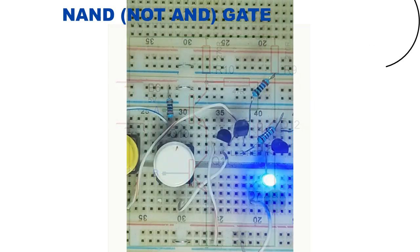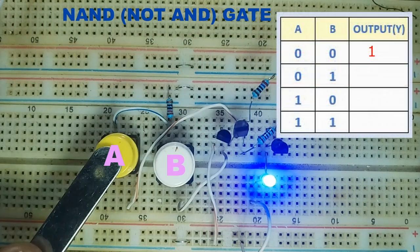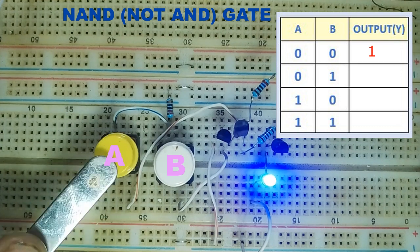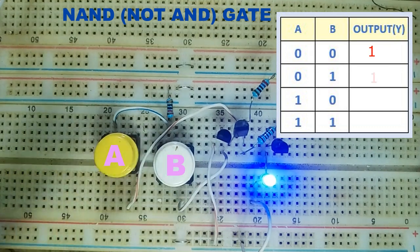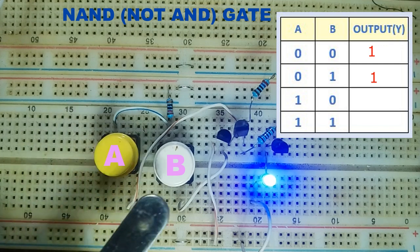The circuit on the breadboard is also implemented using 3 transistors. The first 2 form the AND gate and the third one is for inverting the output. Input A and B are currently at logic 0, but the output is already at logic 1 since our LED is turned on. Add that to the truth table and let's proceed.